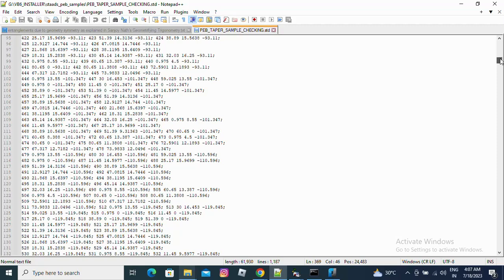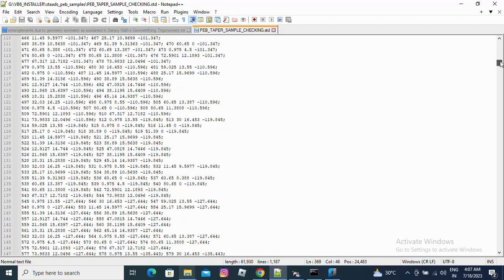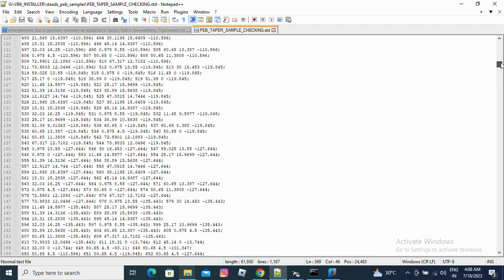We can compare the stage of plated tapered sections used, and we can get frame wise weights. We can get the Z elevation wise weights, the thickness wise weight report, and the total surface area for sandblasting. We can calculate an overall estimate while we are doing the design work and optimization work.